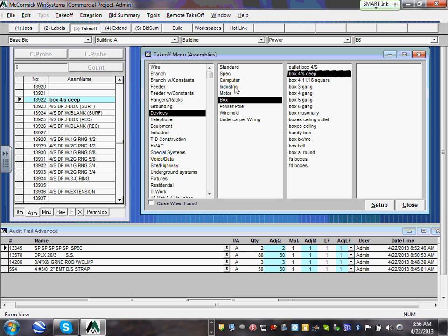Very easy. A room like this, guys, if you put 3 junction boxes here, one junction box here, one junction box here, one junction box there, and shoot the EMT conduit, 3/4 of an inch, in between them. And from these junction boxes, you take a fixture whip, which is MC cable, into each one of them. Done.